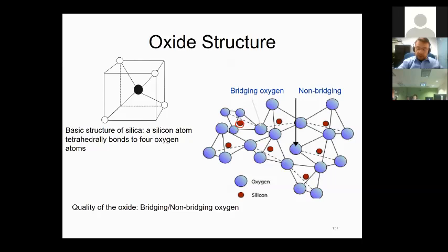Once they're bonded, they create this very short range order, so there might be some oxygen atoms that are shared between these tetrahedral networks, like this one here that is shared, and the others might just be non-bridging, so they may not be connecting these consecutive networks.